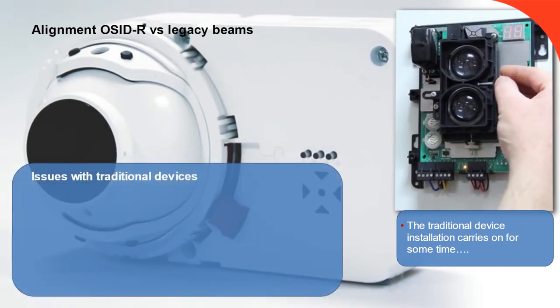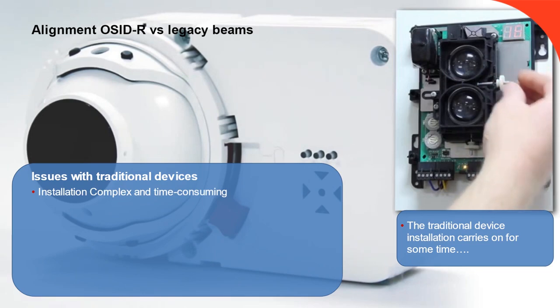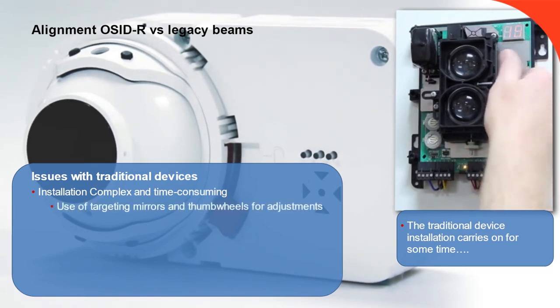The 6500, or 1224 in this case, used for comparison on this slide, uses a targeting mirror to enable the initial alignment. This is a clever process, allowing the installer to get an accurate facsimile of the device's line of sight. However, the system requires the operator's head to be held in exactly the right place to properly see the target. This isn't always easy, particularly if you're up a ladder.